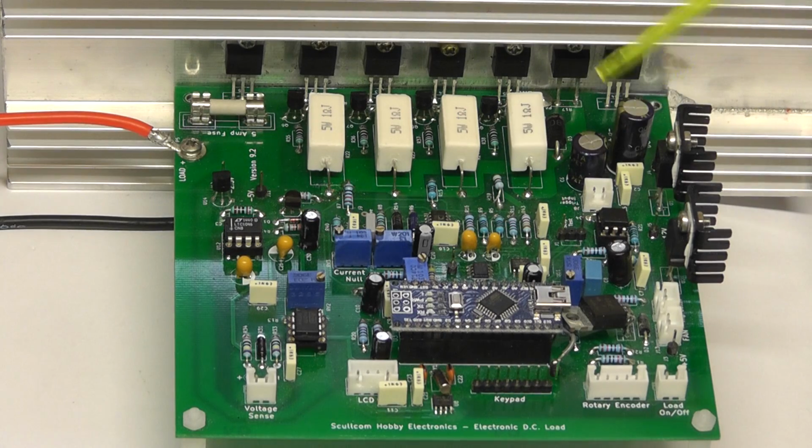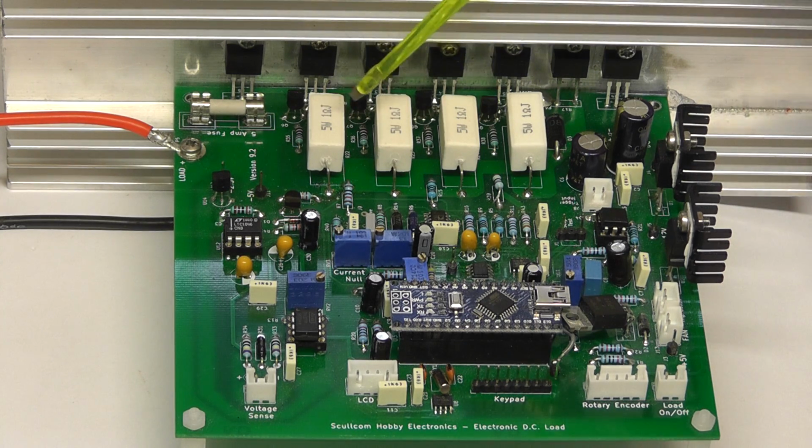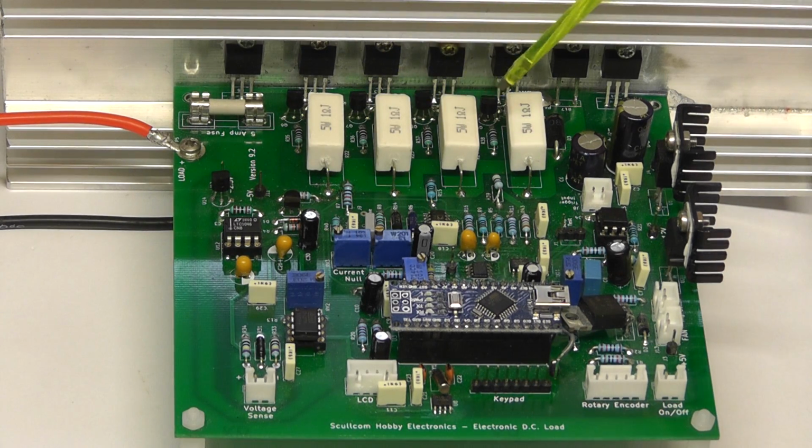Here we now have a view of the printed circuit board where you can clearly see the changes I've made to the output stage, with those 4 power resistors in the source return of the 4 power MOSFETs. Previously we had the 0.1 ohm 3 watt resistors in there, and that's now been replaced with a 1 ohm 5 watt wire wound. You could equally use a 7-watt wire wound, and in fact the PCB is designed to take either type.